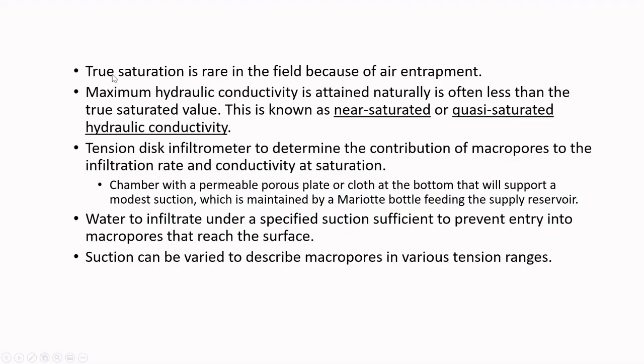Okay, so true saturation is rare in the field because of air entrapment. It means the soil cannot be truly fully saturated, because there is always some air trapped somewhere in the soil. All right, so the maximum hydraulic conductivity attained naturally is often less than the true saturated value because of the air entrapment.